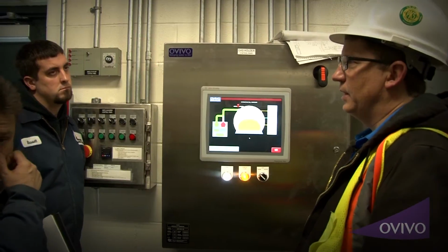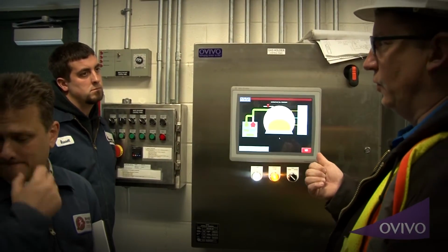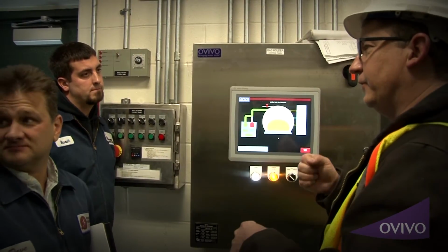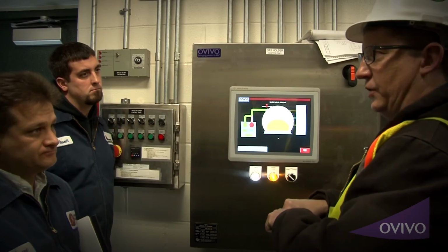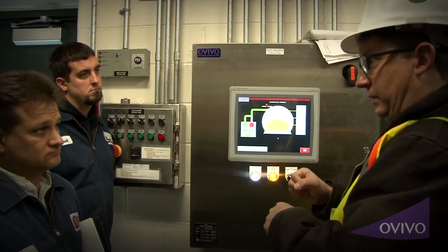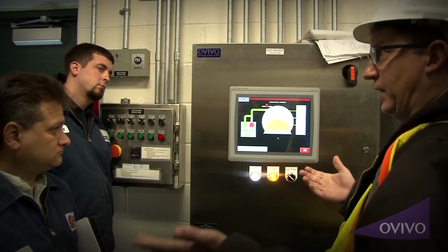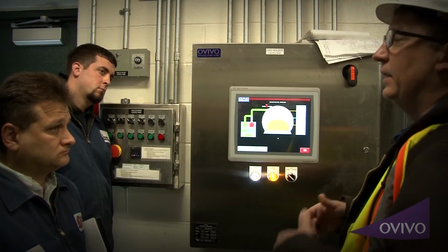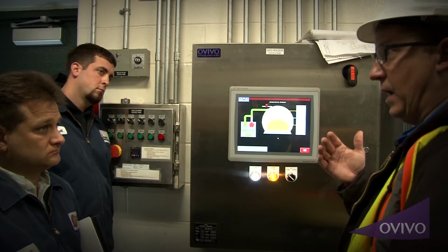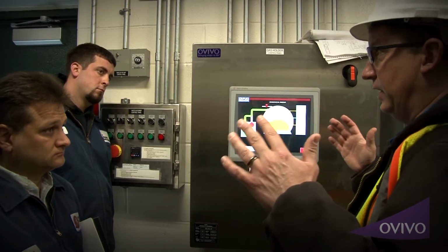Let's say we got that. If you had that, of course, the first thing to do would be to pull off the sensor, run a sniffer into it, and make sure that it is exactly over the explosive limit and that it is reading what the methane sensor is. If that's the case, then we've got bigger issues, because now it's getting methane into the air chamber.